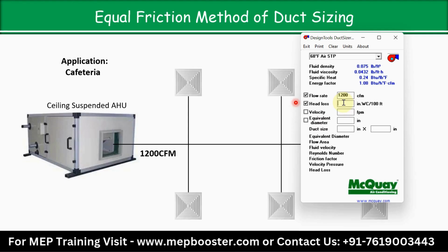if you are designing the duct for a sensitive area or where noise is a factor, at that time how much friction loss do we have to maintain? Sensitive areas such as offices, hospitals, residential buildings. For example, here I am maintaining 0.08 because the range I have already shown you as per different standards, 0.08 to 0.1 inch of water column per 100 feet of duct length.